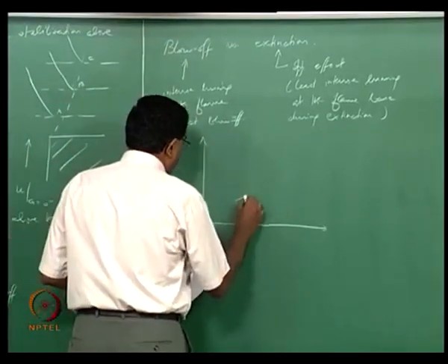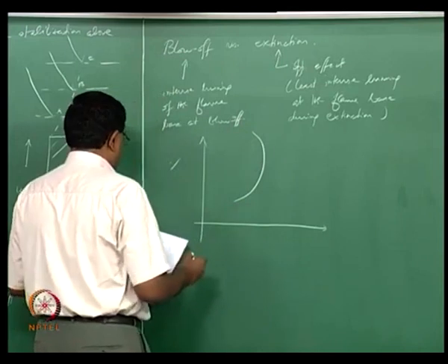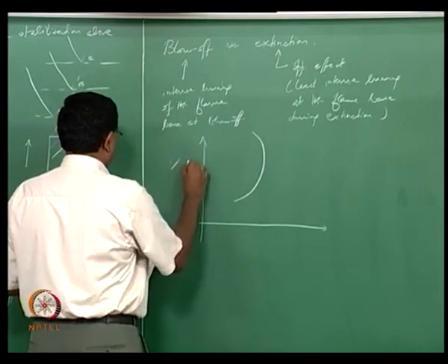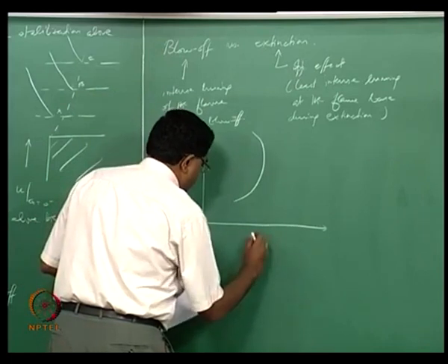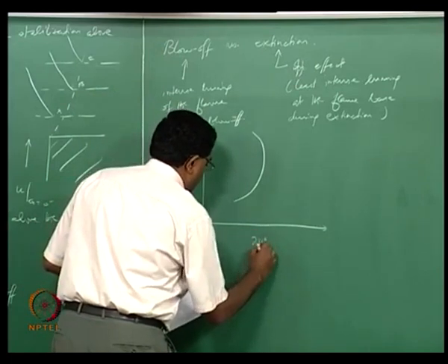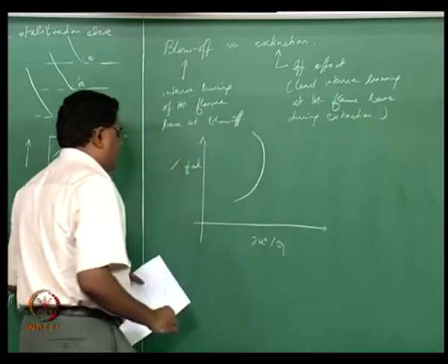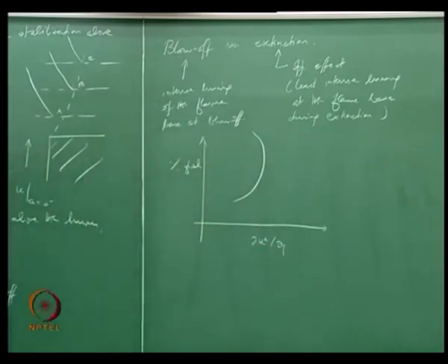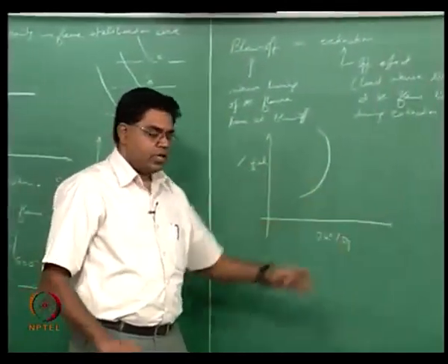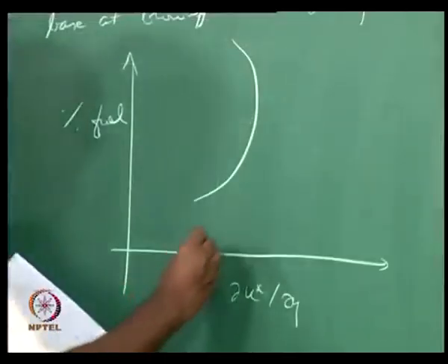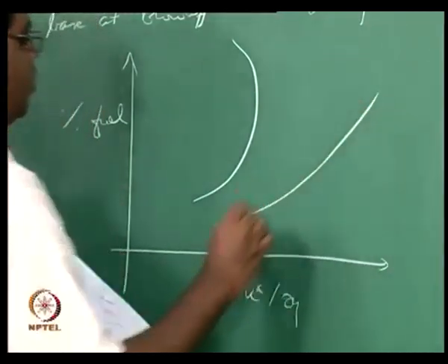One, you have a limit like this, so this percentage fuel, and let's suppose that this is du star over dy, where du star over dy corresponds to a velocity gradient at a flashback or blow off. And so obviously we are looking at two limits, one for flashback and another for blow off.